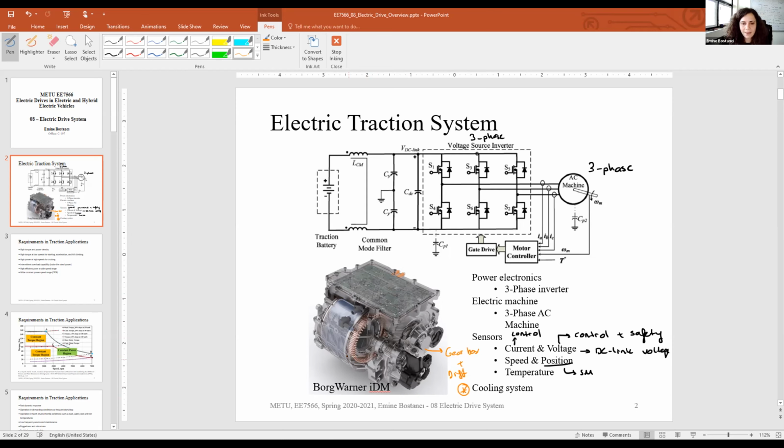If we have a system, we want to have it in different power ratings and torque ratings, and we want it directly connected on the electric vehicle shaft to make sure that we have a compact design. As you know, for the power electronics, the compact design is important in terms of the stray capacitances and stray inductances. So we want to make things closer to each other. But of course, there is a limit. If you make things too close, then they will start to affect each other.